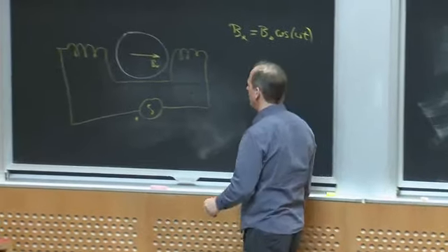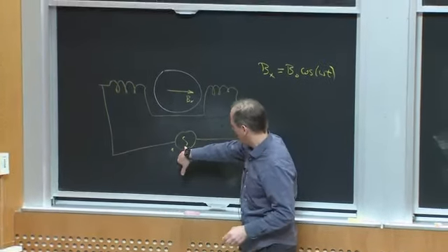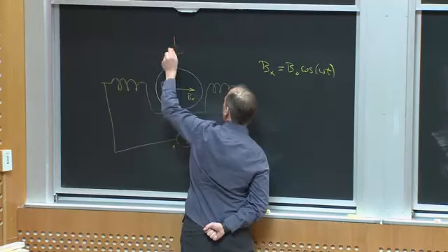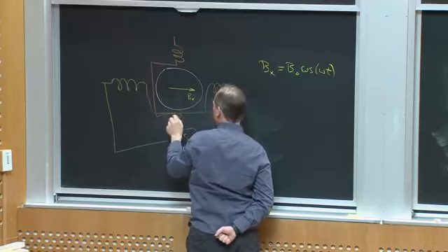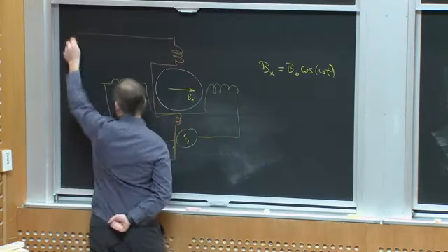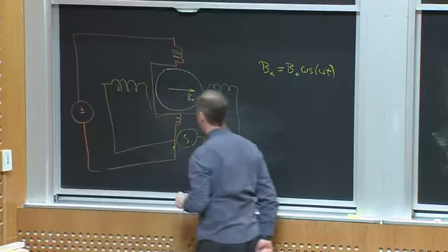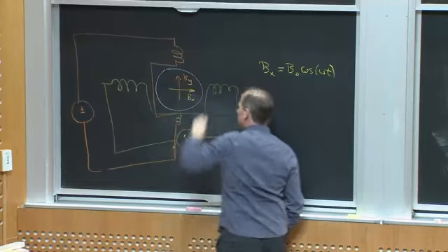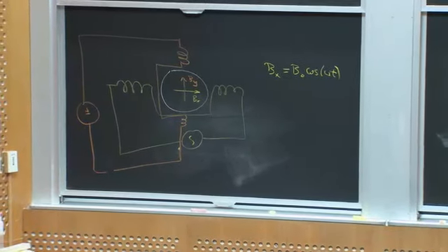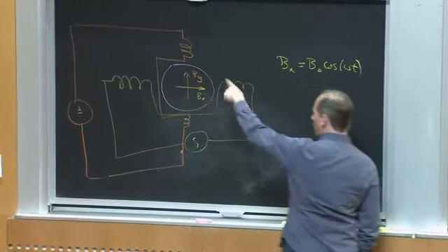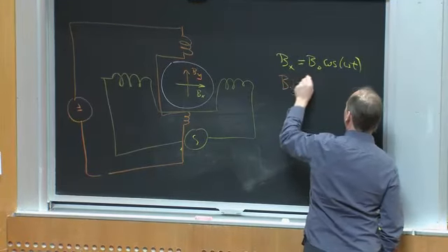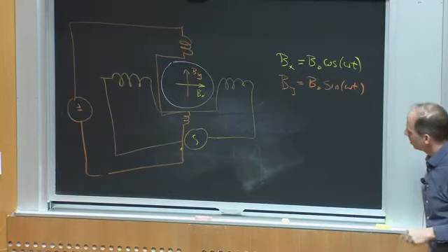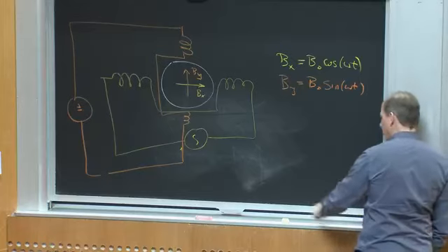But imagine I came and said, all right, that's one phase, right? This could be a sinusoidal voltage I'm driving with. But perhaps I created a second one like this that's perpendicular to it. Right? And maybe with this one, I could create some y-directed magnetic flux density. Okay? Well, maybe the orange set of coils here could create B sub y is equal to B naught sine omega t. Okay. If I did that with both of those, what would I get for a net magnetic field?